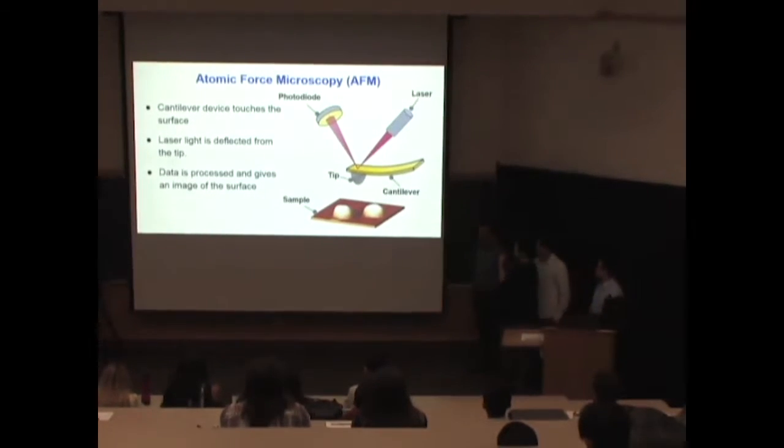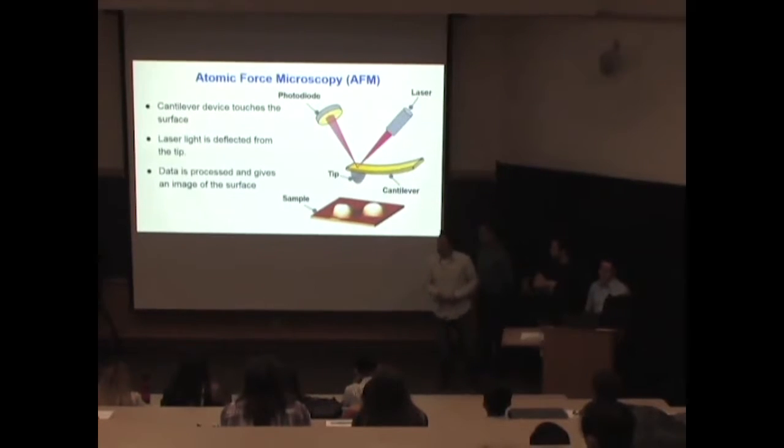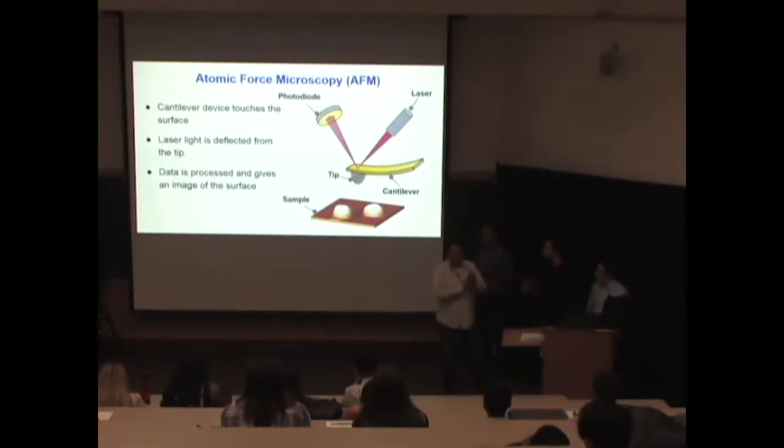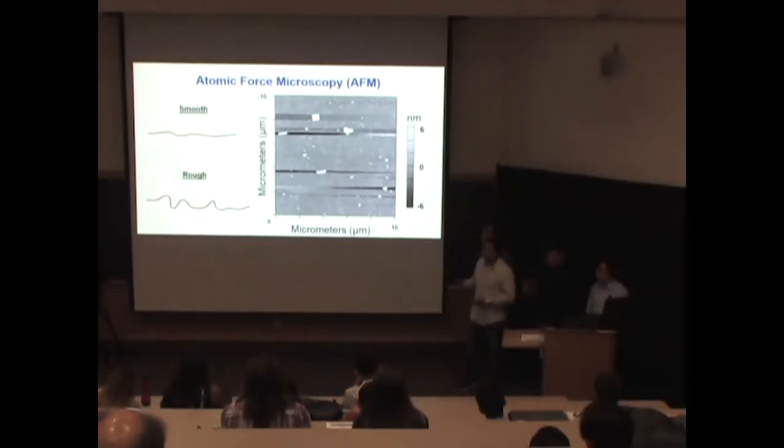On this slide, you can see in more detail what happens inside the growth chamber. All of this is taking place inside an ultra-high vacuum environment, whereby all the air is sucked out of the growth chamber, and along with it, the contaminants. But before that can happen, we need to choose a substrate with a similar lattice pattern to barium stannate, or the thin film that you want to grow. And once it's inside the growth chamber, the substrate is heated along with the effusion cells. The beams travel through the vacuum with the vaporized materials, land on the substrate, and grow epitaxially, or layer by layer.